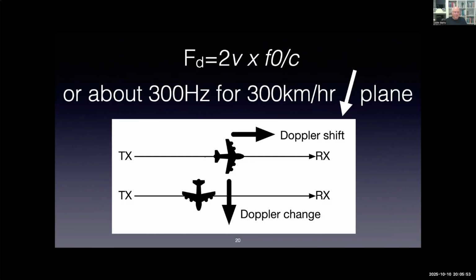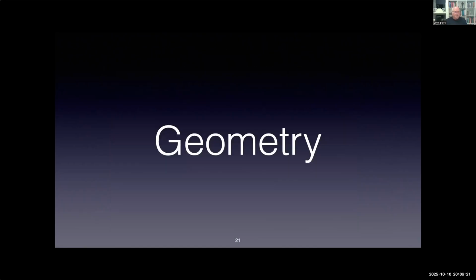Going down the line, in theory, you get a Doppler shift up and a Doppler shift down. The two cancel out. However, for an aircraft that's actually crossing the path, you will see exactly what is displayed in that formula. You will get a Doppler shift, 300 kilometers an hour. You get a 300 hertz change in your signal frequency, and that can be pretty hectic for decoding.